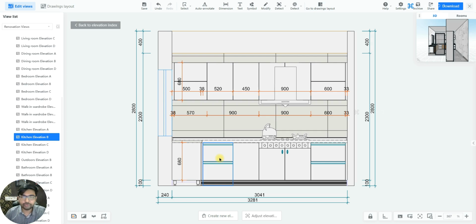So for that, you will eventually need to depend on your custom furniture drawing or your cabinet production drawing, like what we addressed in our previous session. So if you don't have the requirement for the internal elevation of the cabinet, and if you're not concerned about the details of your cabinet in your 2D drawing, something like your layering, swing direction, cabinet numbering or so, you could precisely go for your construction drawing to generate the 2D drawings for your cabinets here itself.